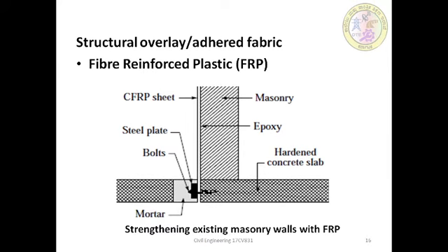The surfaces should be roughened first by grinding and then cleaned with high air pressure, and holes are filled with epoxy mortar. Then the small holes are filled with epoxy resins. The FRP sheets are fixed to the surface of the masonry substrate by the epoxy resin, crosswise on one or both sides of the walls.